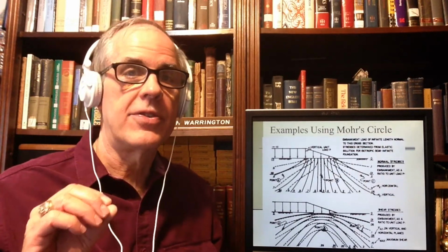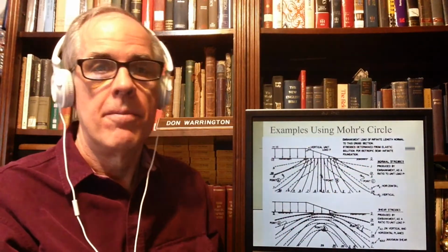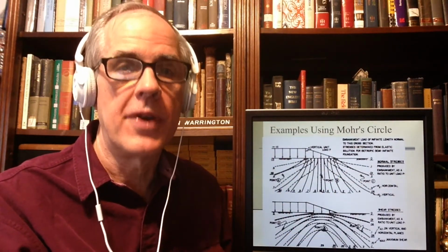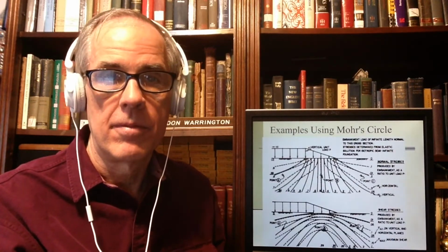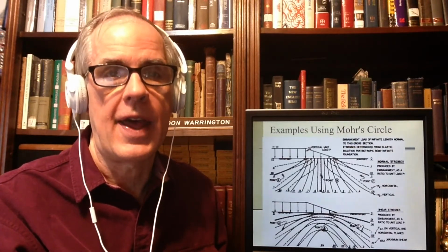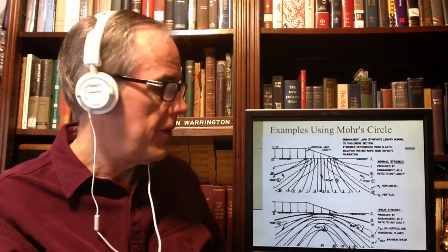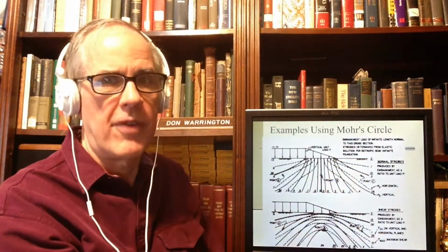So let's say then that both directions, if it's infinite in both directions, it is referred to as a uniform surcharge. If that happens, or if I tell you that happens, then what you assume is that this soil starts out with a zero stress here, with effective stress increasing in the normal fashion.